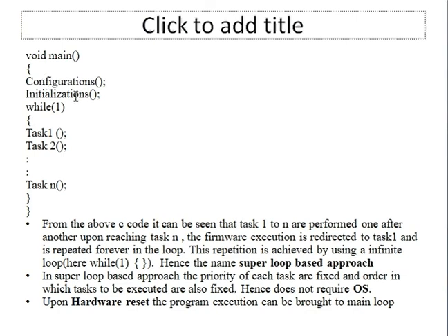Also you will call the libraries like startup init and system init. Also you will invoke other libraries like system LPC and startup LPC. Then you write the main piece of code inside the while statement, and that will be running again and again.